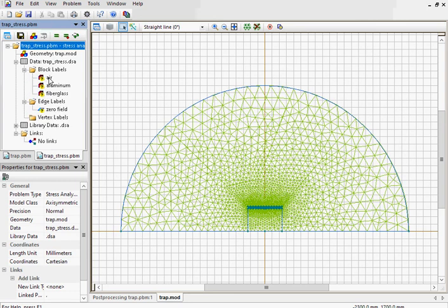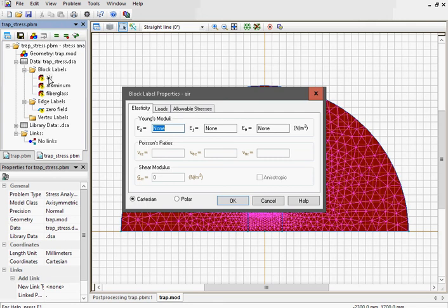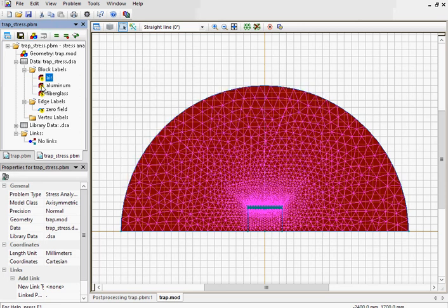We do not calculate mechanical stress in the air, so for the air I do not specify any values, just open the dialog and click OK. Now instead of the question mark we can see an exclamation mark. This mark indicates that this label is not an unknown label. It is a label with empty dataset, and this label is excluded from the simulation analysis intentionally.